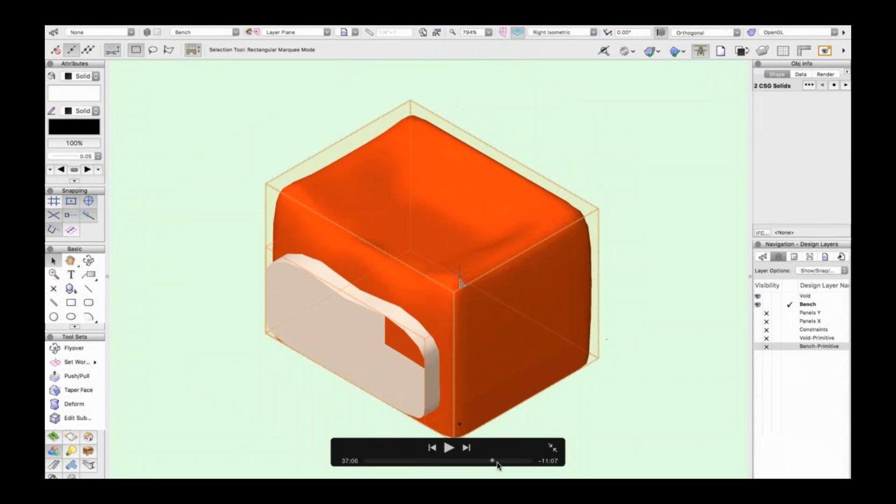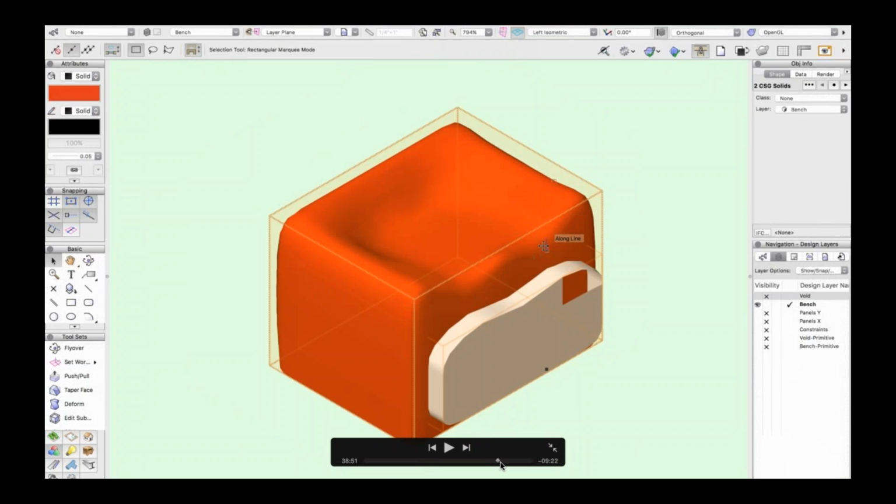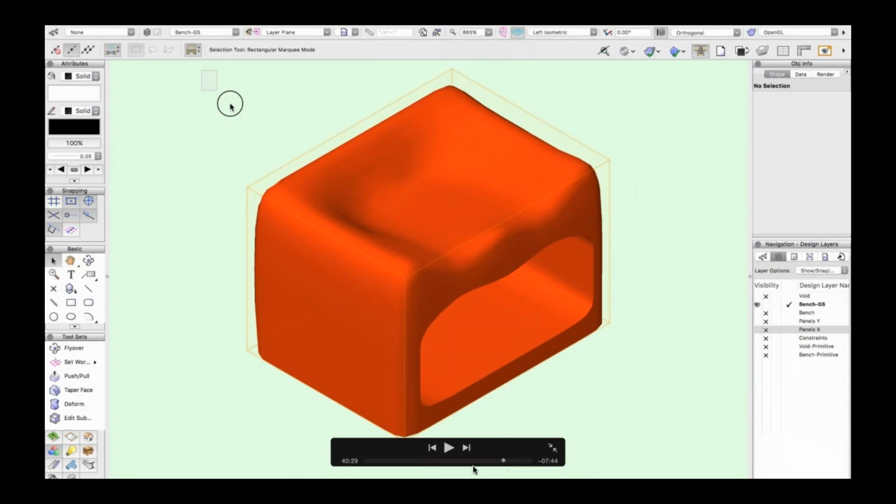And what I want to do is actually subtract that object from that particular form. Now, how does this work? Well, you can't subtract a subdivision object from another subdivision object. And that's really important to note. Currently, in 2016, you cannot subtract a subdivision object from another subdivision object. The primitive and the subdivision object are essentially synonymous, but the primitive is that organic shape you're seeing there.